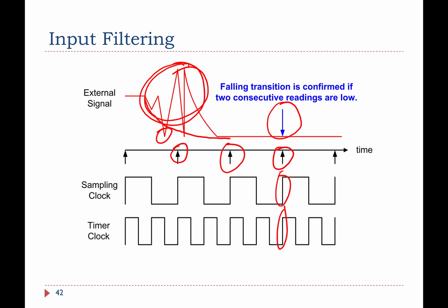And so now notice the sampling clock is basically showing that it's the timer clock, and it's going to be some multiple of the period, so that it can actually detect the transition with some sort of filtering mechanism. And you can do it, as I say, no filtering, you can do some filtering, you can increase the filtering even more, and so forth.